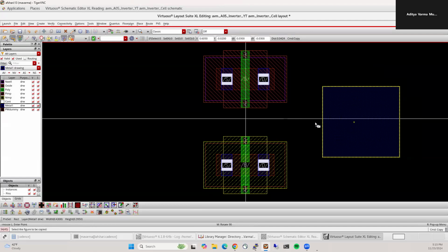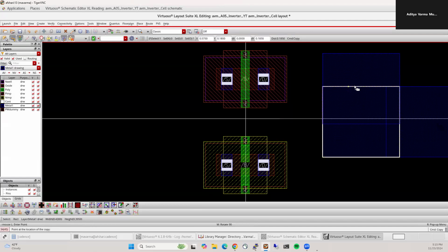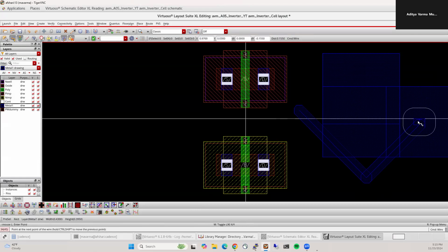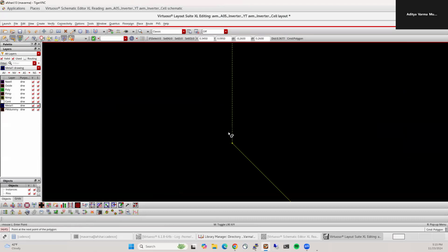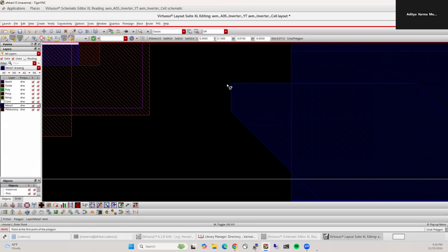And then if you click C, then that can create copies, for example. P is for creating a path. So that's a path, for example. I don't use that much, but it is useful in some cases, especially in digital design. Then Shift P creates a polygon. Again, these angles are only determined by the diagonals that we set up in the settings just now. And you should stick to that. Don't try to create polygons in any random directions because they won't meet DRC specifications. Okay, so that's a polygon, right?